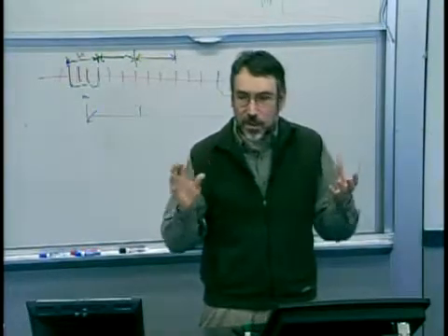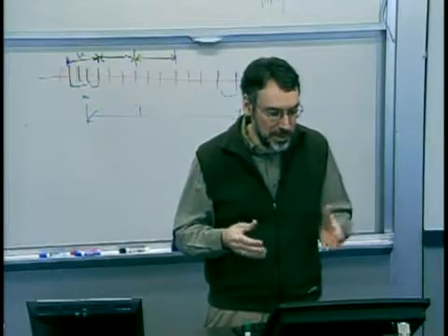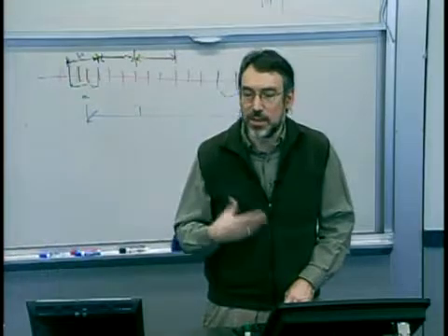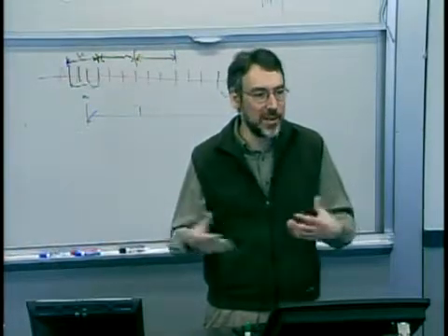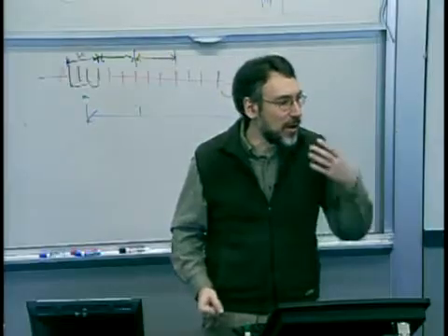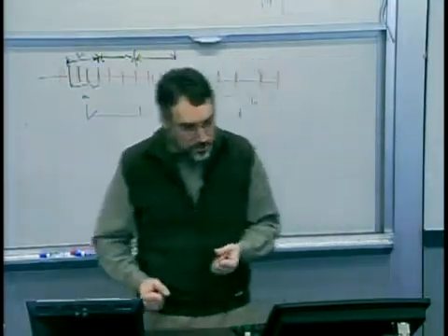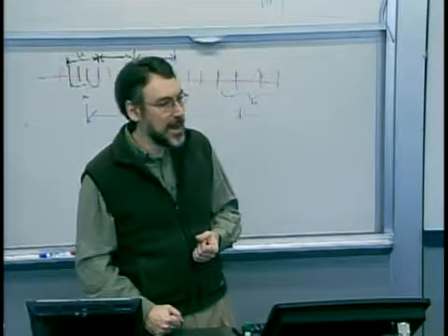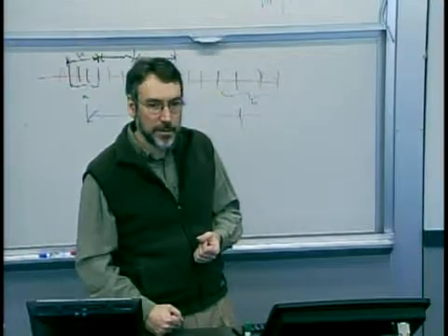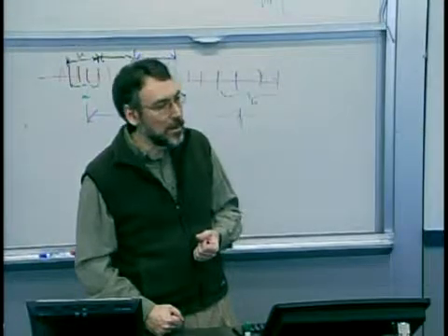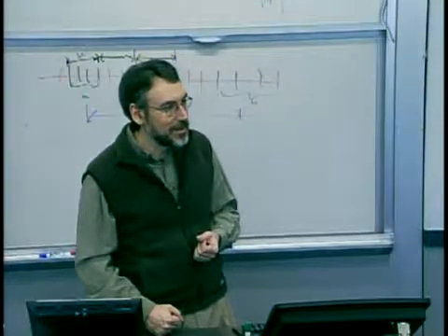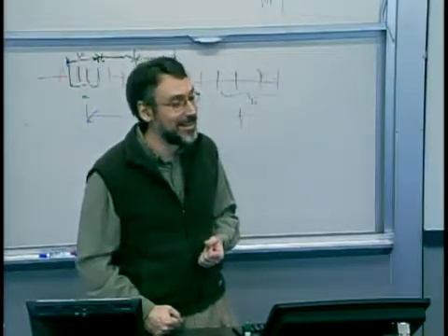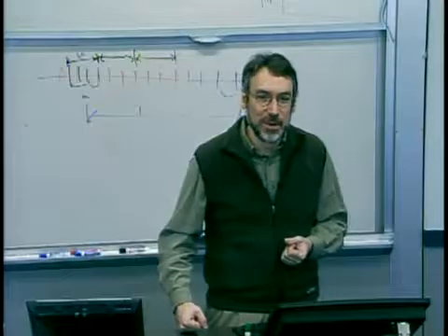To relate the two, a good way of thinking about it is the Cp and Cpk, or an expected loss function. What's nice about Cp and Cpk is we've basically normalized away, so that if I came up to you and told you my process has a Cp of 3 and a Cpk of 2.5, you'd go, wow, I'm impressed. That's a pretty good process, or awfully loose spec limits. One of the two. You don't really know.